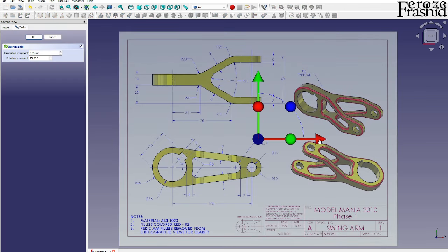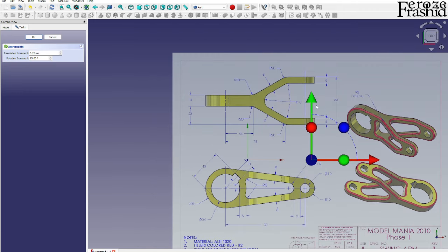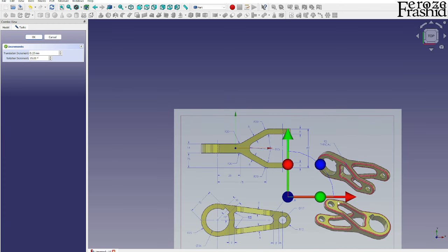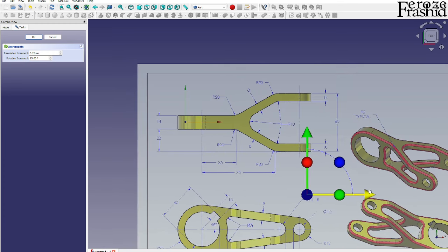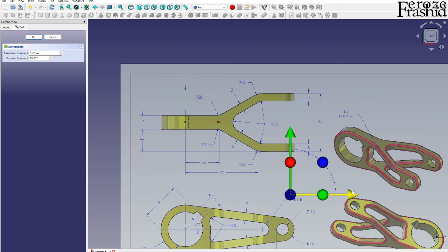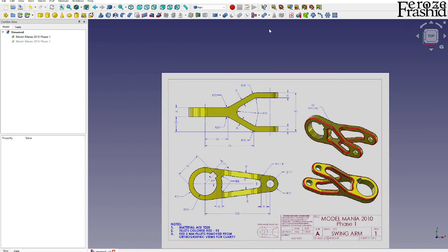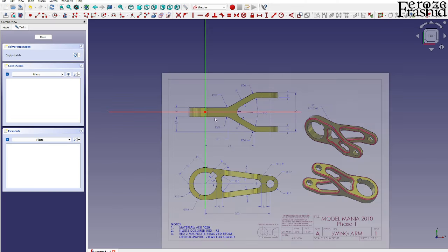Now on this phase 1, I see I'll have to approach this from two directions, and that way I will probably be building it as a common intersection of these two extrudes. So I'll be building this model top down and front and back. Then we'll be doing the common intersection Boolean operation from here. I'll be using the part design workbench, and let's start with the top down sketch on the XY plane.